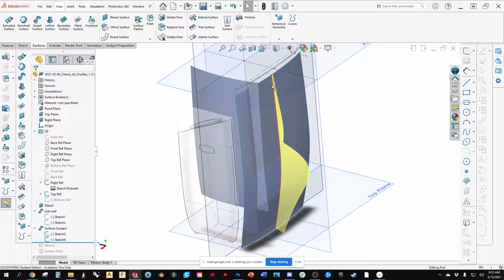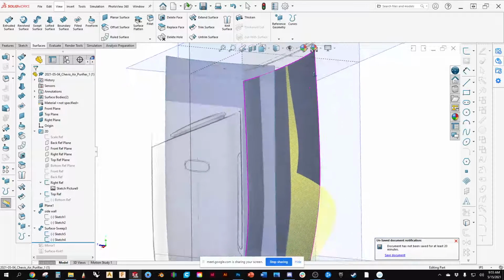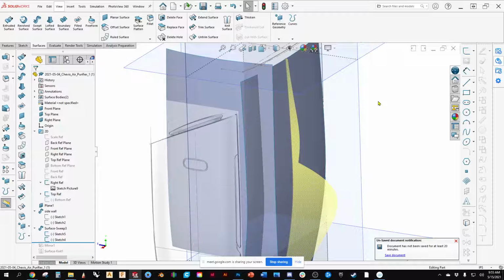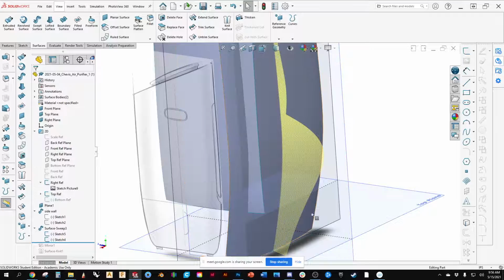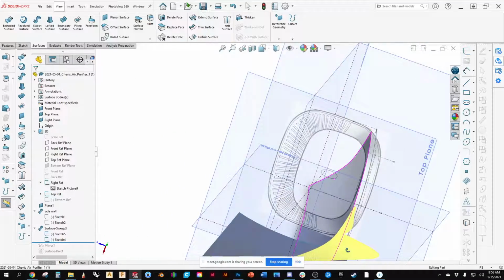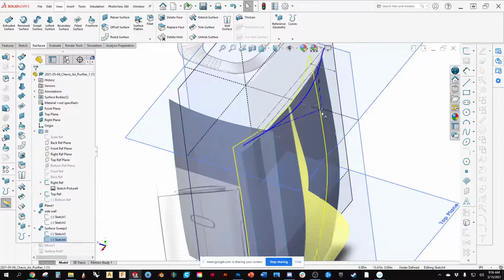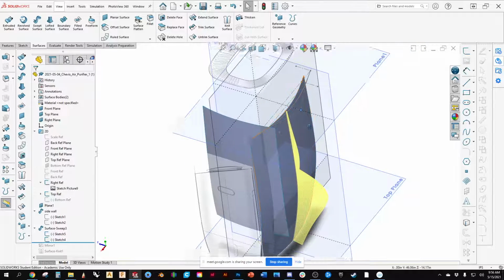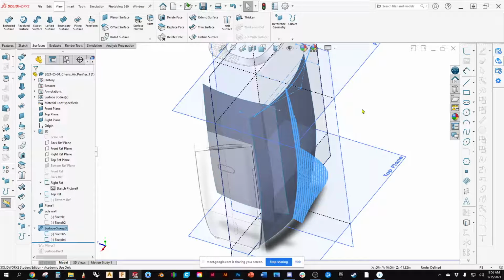So here I've got this surface built. I used a swept, which means that this surface, the start and end, is always going to be the same. When I say it's going to be the same, it's going to be controlled off of this CV. You can see as I'm moving this that the bottom's moving at the same time. Okay, so let's just get out of there.